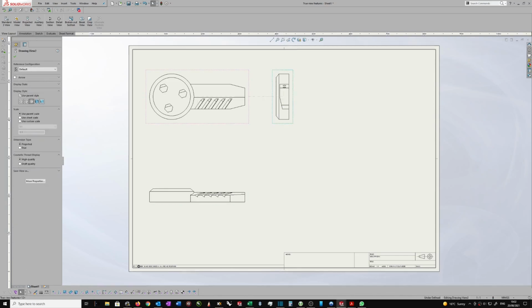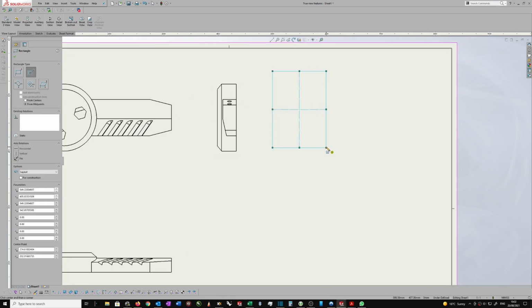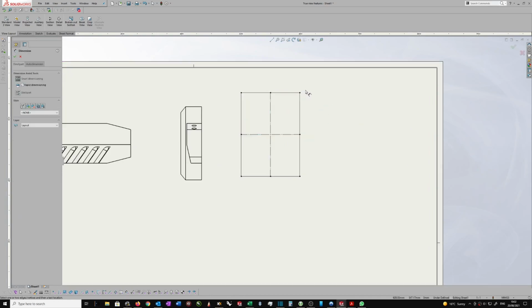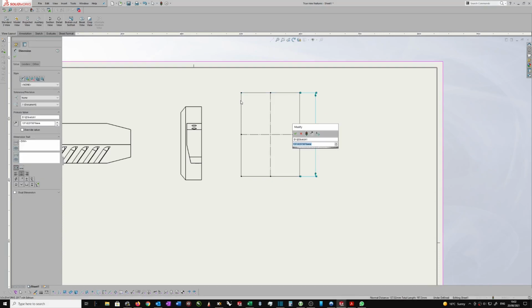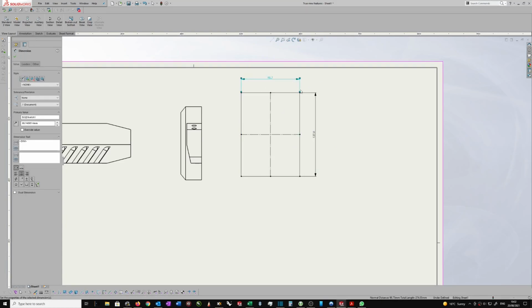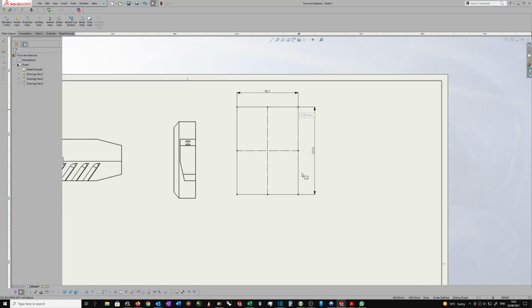This is much nicer. So quick reminder, I had drawn a rectangle. And what else had I drawn? I think that was it. It was a rectangle and something else. And the point was dimensioning using parallelism. So I just need to refine what I said yesterday, that when you're dimensioning anything which obviously has parallel sides, then you shouldn't dimension to the points. You should always dimension to these ends, and what you're dimensioning is always parallel.